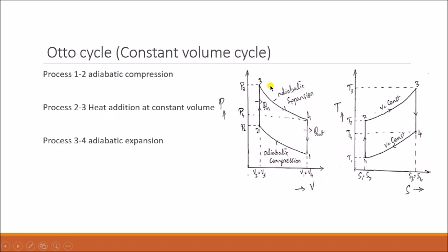The heat is supplied to the gas, and due to the energy absorbed, it starts expanding and releases the energy to the piston. The piston starts moving downwards, or to the right side. During this adiabatic expansion process, the expansion takes place and no heat is added or rejected. What happens here is that the pressure starts decreasing again, and the volume starts increasing.